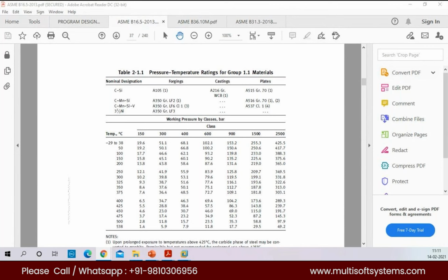Okay, so I understand. There is no problem. That is the consideration, and that is my understanding too. Everything has some limit, and we have to take care of fatigue analysis. For 20 years, 30 years, the plant has to run, so whether this material can withstand that. If you go for the worst condition of 600 and the allowable was less, if anything happens, that will not be acceptable, right? So we have to make some limit. Up to 427 we can go for carbon steel. Like some limitation we are creating. We can't go for the worst condition.